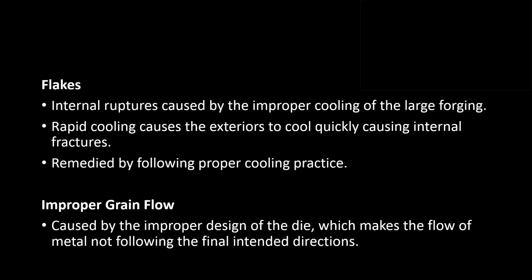Flakes are basically internal ruptures caused by improper cooling of large forgings. This is because of rapid cooling. The surface gets cooled fast, but inside it is a little hot and cooling slowly, so obviously a tension will arise, and due to that a crack will happen. So simply, do proper cooling and you will not get flakes.